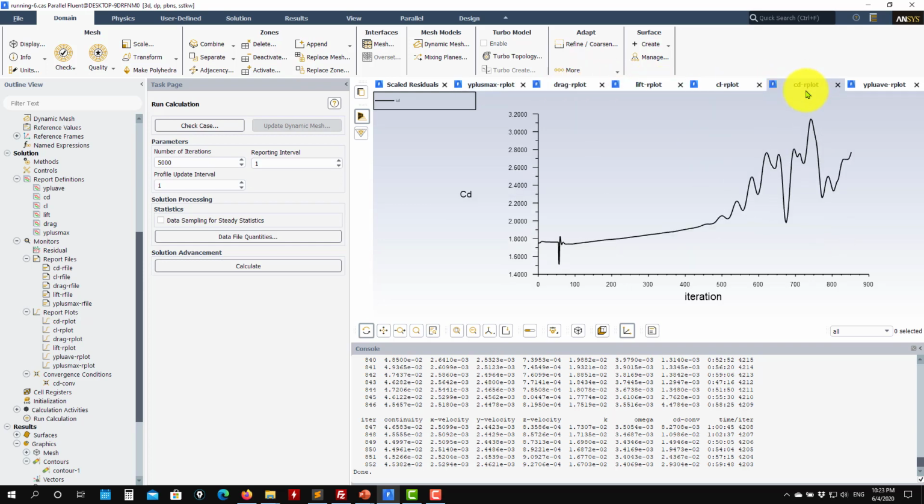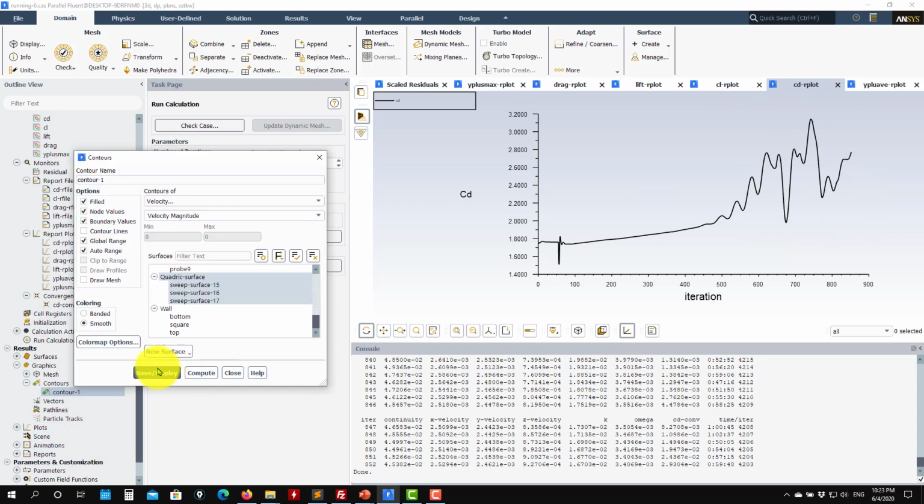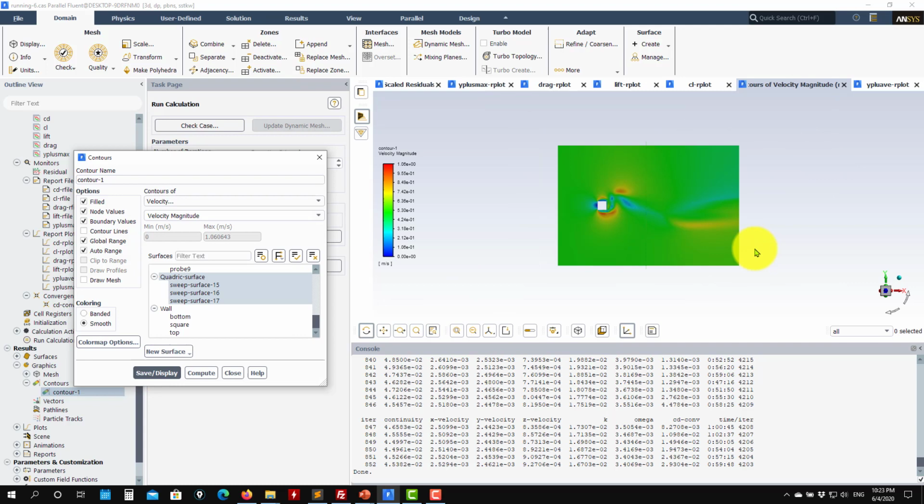So you have the lift and drag forces. And if you visualize here, you will see that you have some shedding. So this is an advice. Sometimes it can be a good idea to first start using a coarse mesh in your problem, and then probably switch solver. So the coupled is very fast, so run with the coupled, and as you get to a solution, then switch to the SIMPLE and run a few iterations to see if there is some different behavior.